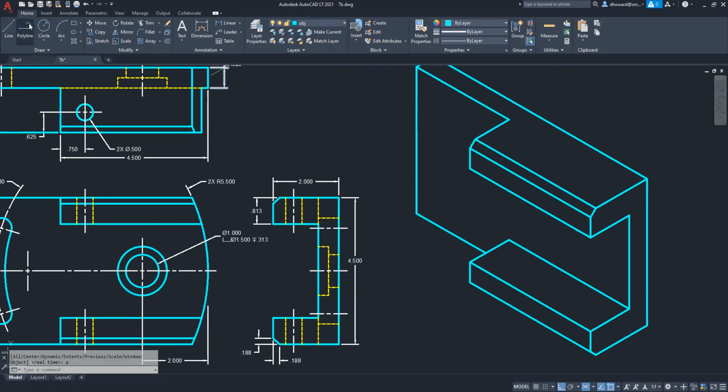Whatever. For this one, because that corner is right there and it's nice and easy to grab, I'm gonna measure from that. Take my line command here, click on that corner and pull in this direction the distance of 3/4. So 0.75, and then come over this way to the center, and that distance is also 0.75. So now I have my center point marked. It is the end point of that line right there.